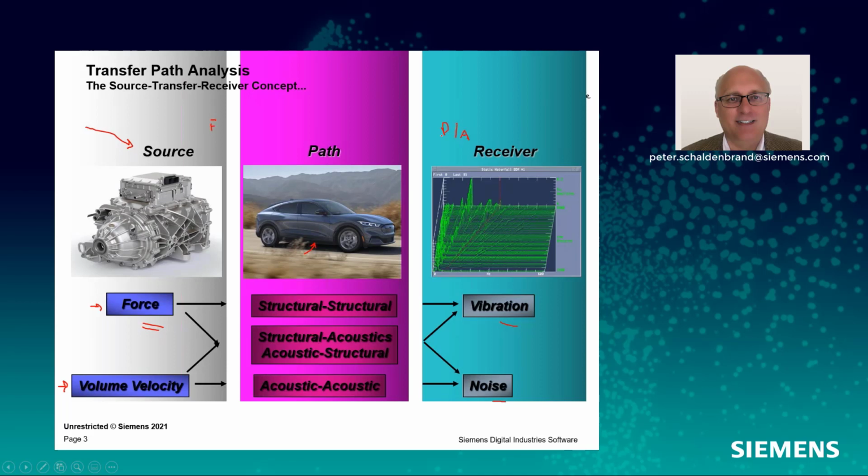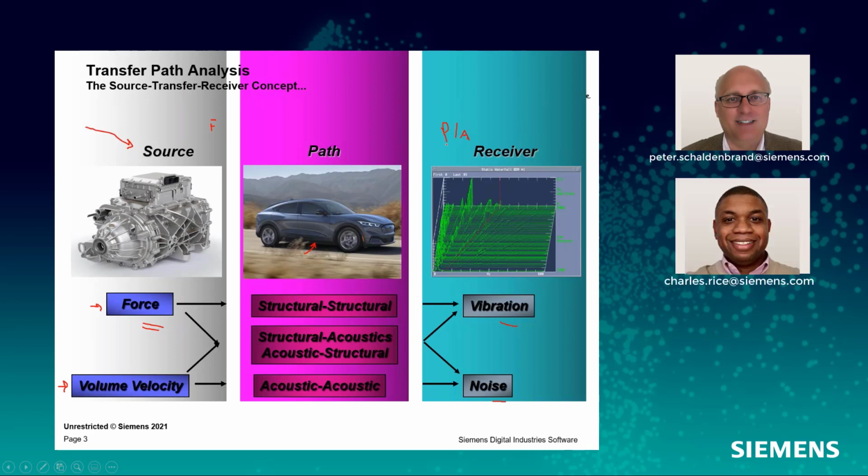Do you know what that special measurement would be, Charles? I'd say FRF. Yeah, FRF or frequency response function. That's a very typical thing we'll use to characterize this part of the problem. We'll measure operating data over here. So when we quantify what the source is doing, we're looking at operating data, and we'll talk about it, but it's actually the forces that are coming out of the source.